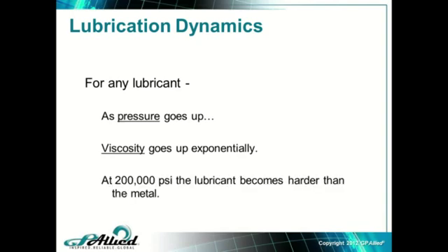And when we get as high as 200,000 psi, most greases and some of your standard oils actually become harder than the steel they are servicing. Now, that's a bit tough for people who are new at this to swallow, but you put enough pressure on grease, that grease actually becomes harder than the steel it's touching. And it's that characteristic that makes bearings and gears work the way they work.